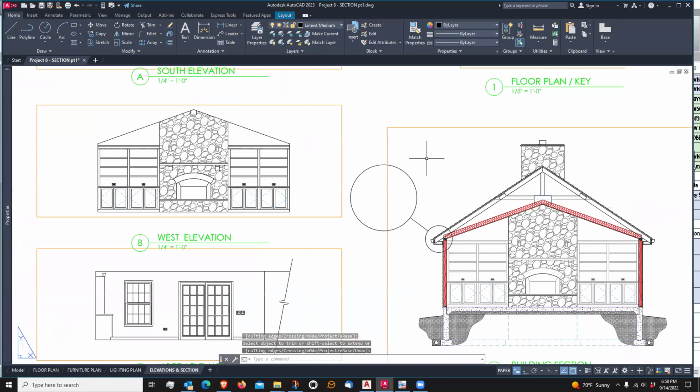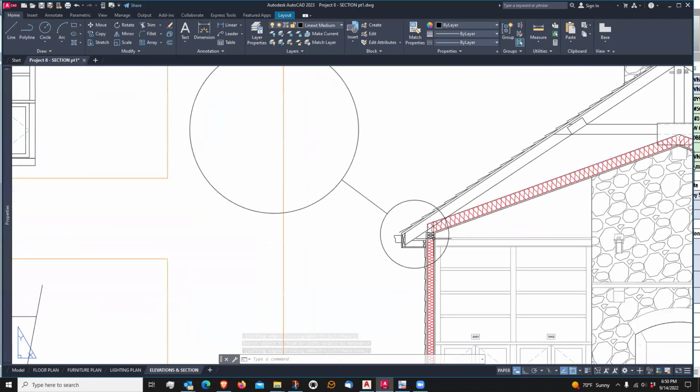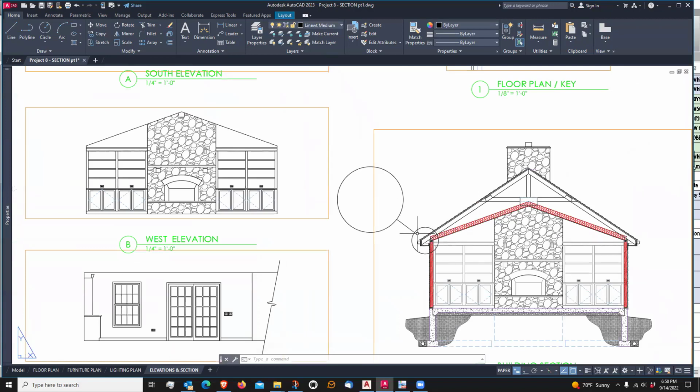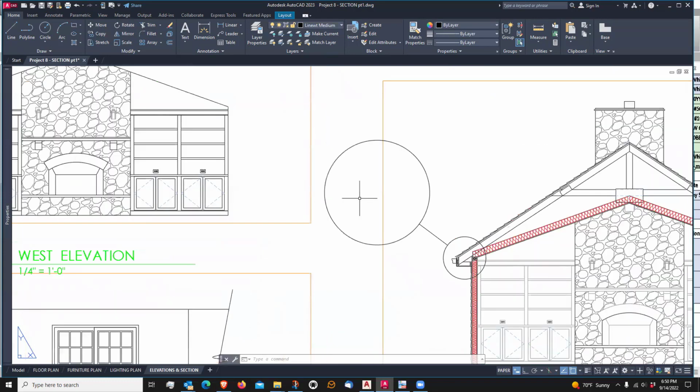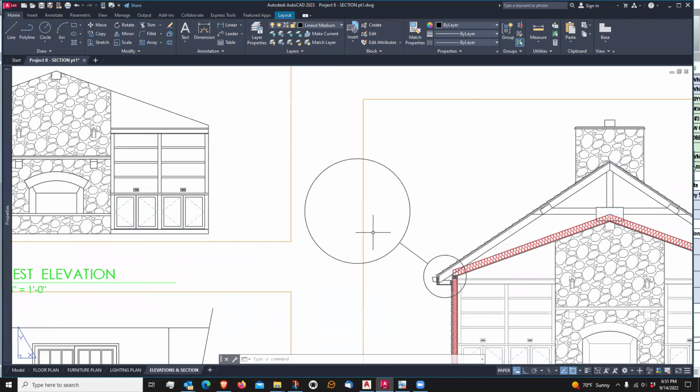And by the way, I am in paper space right now. So, okay, what this is telling the contractor is this little circle here, here's the blow up of it right there. So do we redraw this? Heck no. What we'll do is we'll turn this circle into a viewport and then blow up this detail here in this circle. So let's do that.